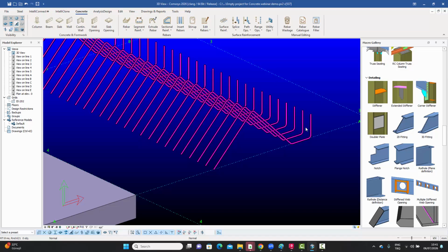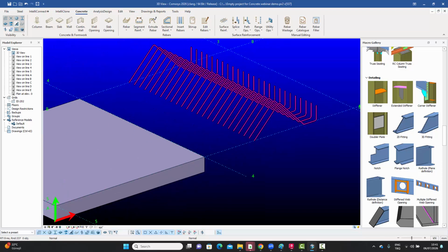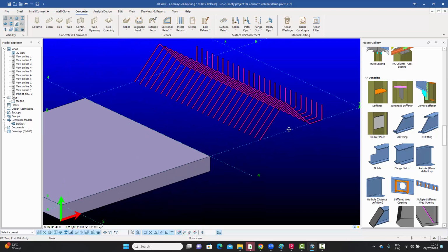And these shapes are pretty simple, usually straight bars or L-shaped bars or U-shaped bars, and the stirrups and cross ties and all that. So having very irregularly shaped bars can create problems at the site. So it's always a good idea to remain within the shape codes.